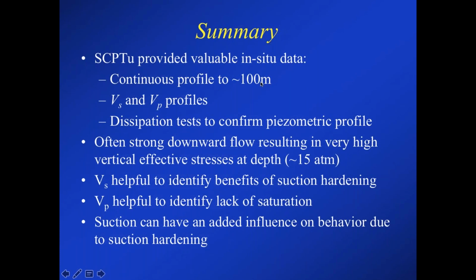And so, I'll just take a moment here, as I know Gregg sponsors these webinars. This was not Gregg CPT data. It was actually Context data from South America. So I congratulate them for such nice quality seismic CPT data down to almost 100 meters, collecting both shear wave velocity and P wave velocity data.